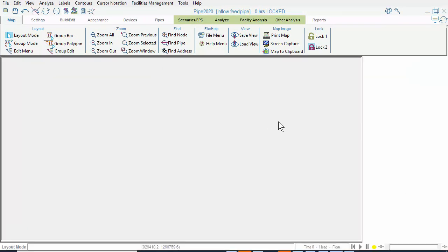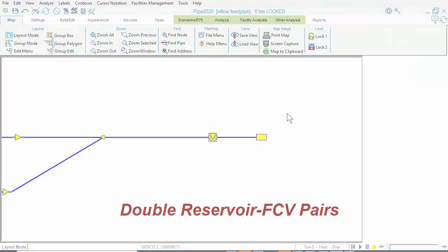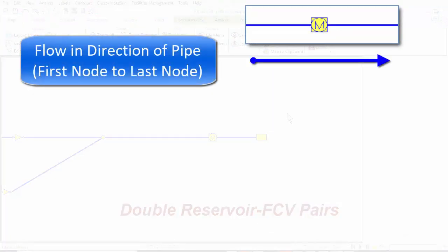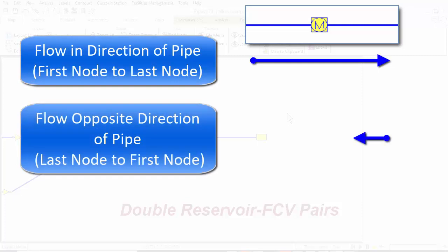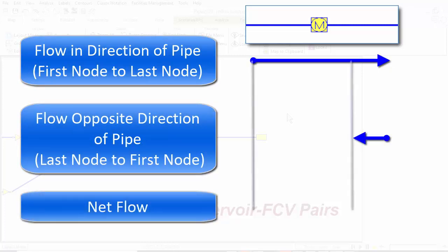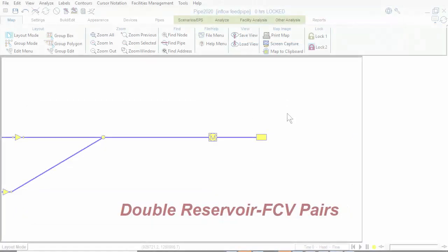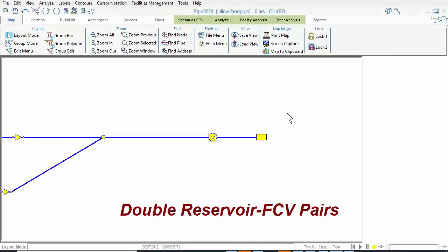Inline meters actually record net volume, so if there are any flow reversals, that amount would be subtracted from the total. So, if this is not taken into consideration, inaccurate results could be obtained. However, feed pipes only contribute flows to their tank in the direction in which the pipe was laid out, and the setup methods shown above only produce unidirectional flows. So the inline meter always records correct data for these types of scenarios.